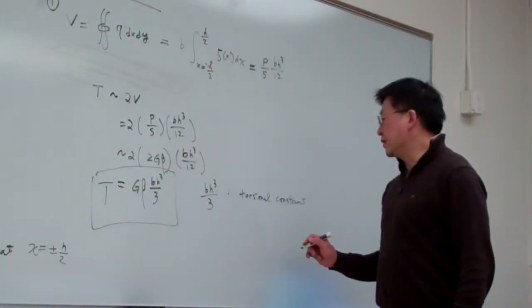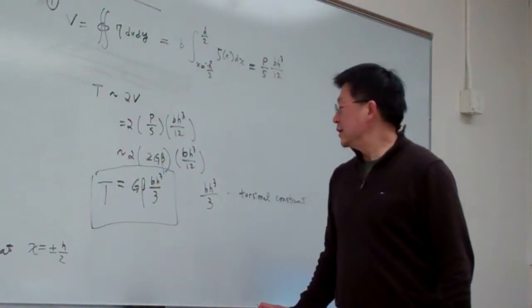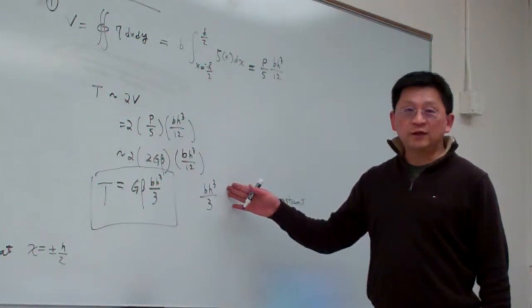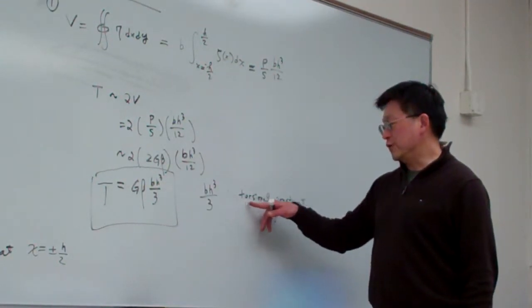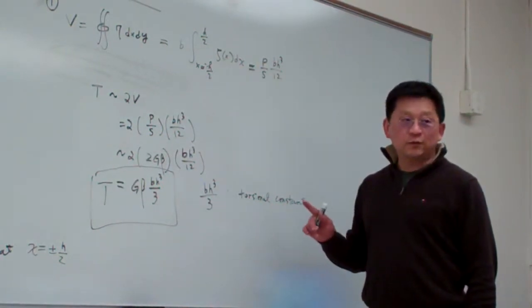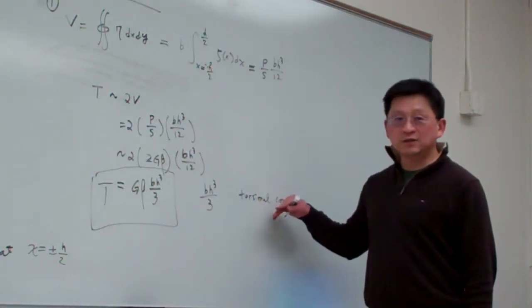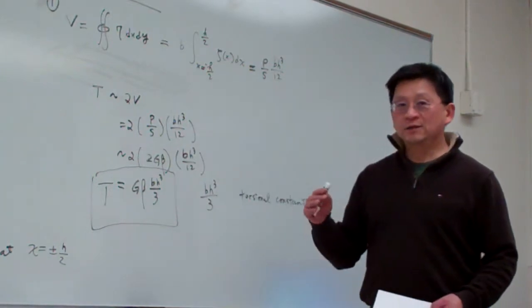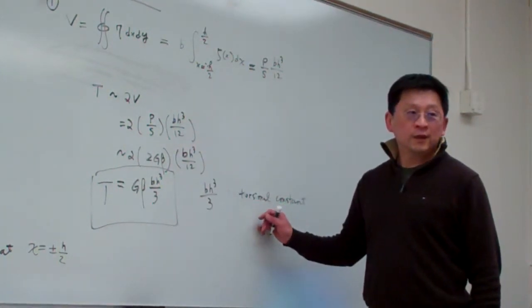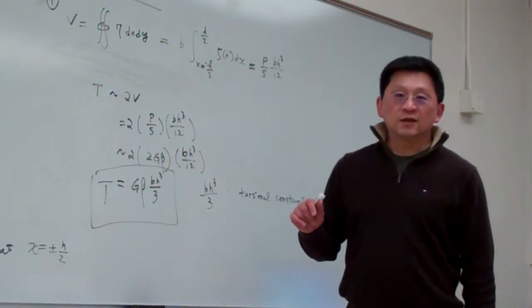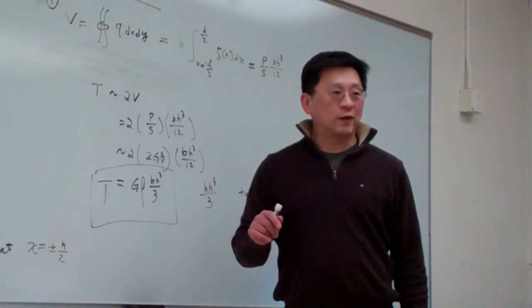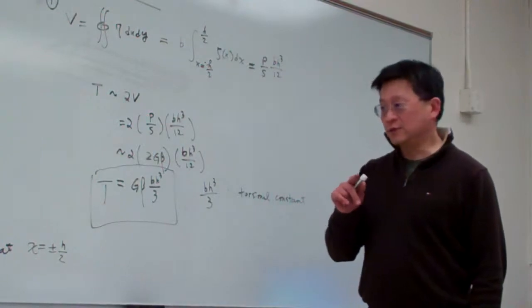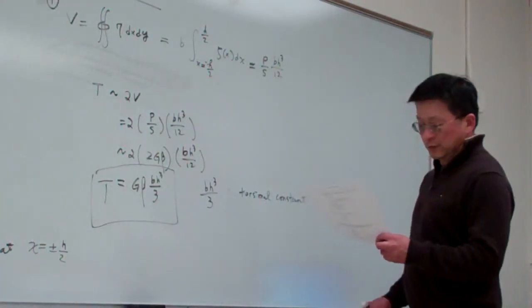I think I made a mistake in the previous lectures: everywhere I said polar moment of inertia, that should be replaced by torsional constant. The torsional constant is different from, and larger than, the polar moment of inertia. For a circular shaft, by chance, the two are just equal. The explanations are given in the handout I emailed to everyone last Friday. If there are any questions, wait until we finish this section, and then jump back to you. We good? Okay.